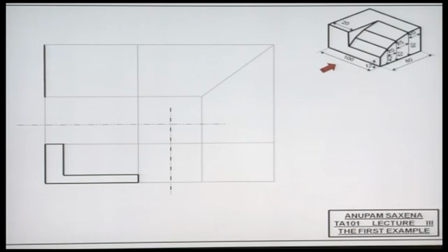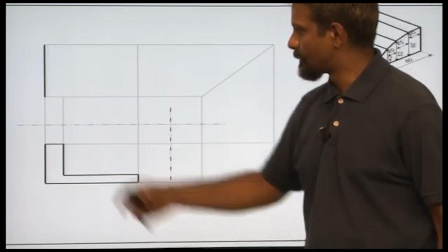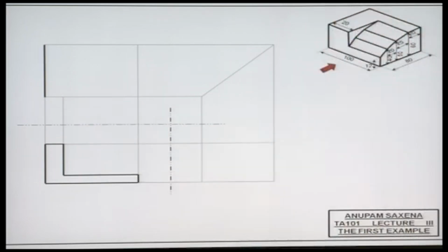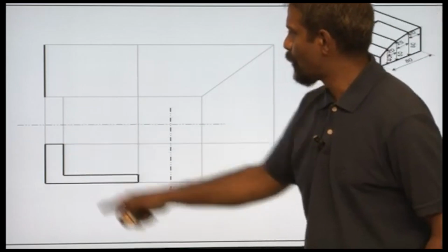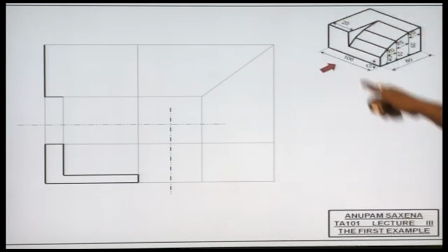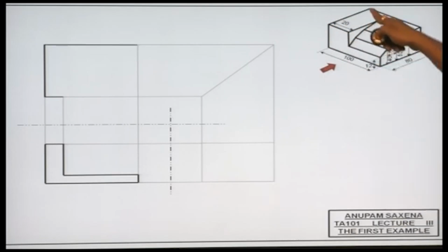Let's try to look at the object from the top. I have drawn this edge. Okay. Now it's always a nice idea to work with the projection lines because you are kind of sure which entities or which features of the object you are representing in whichever view. Okay, so I project this point upwards, and then I show this edge, and then I have got to show this edge over here, but we'll come back to that later.